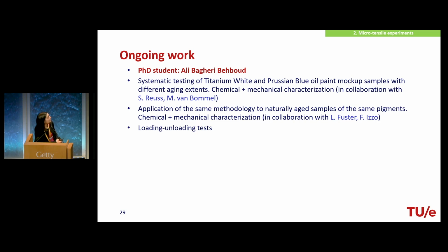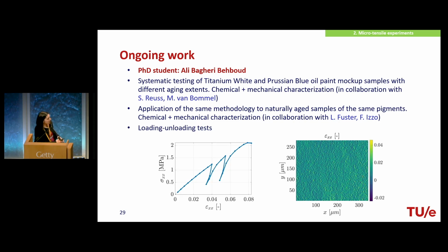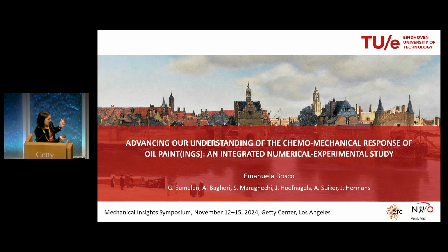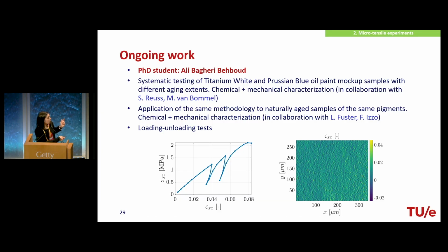And finally, what I find very interesting, which I think also relates to a better understanding of the response of the paint, is that we are not only doing tensile testing, but we also try to do loading and unloading, because I feel that there is still a gap in the knowledge on the irreversible response of the paint. So you see that here we load the sample up to a certain point, then we unload, then we load again, then we unload up to failure.